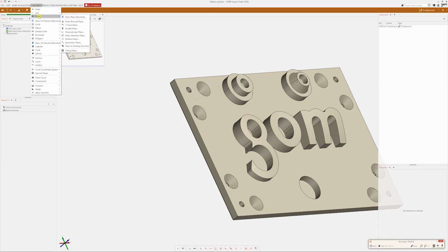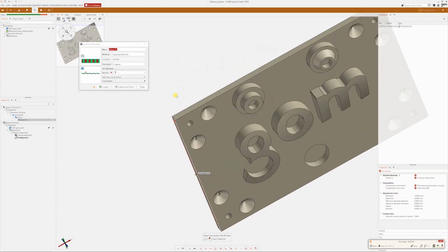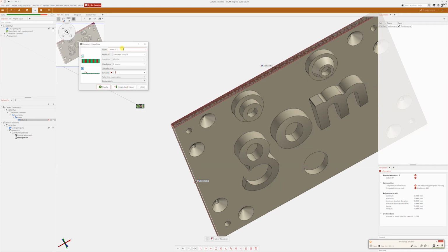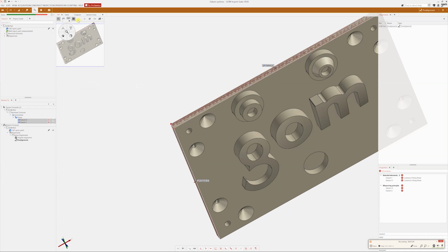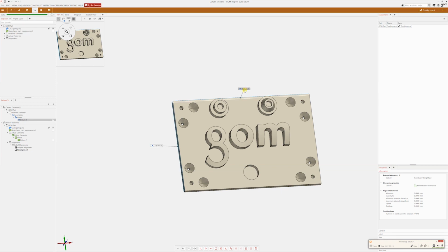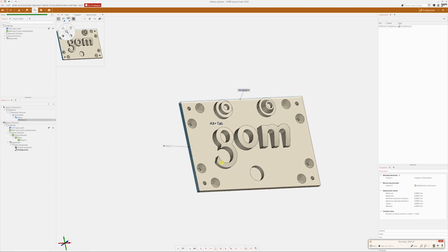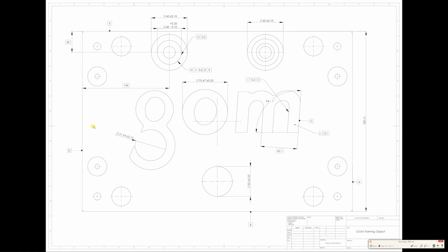Okay, let's construct a plane, fitting plane. Let's call this datum D. Let's make it as a best fit for now, and let's take this datum E and close it. Put the measuring principle as reference construction, and now we have datum D and datum E, plane elements where the drawing indicates exactly on the surface. So as we see here and here.